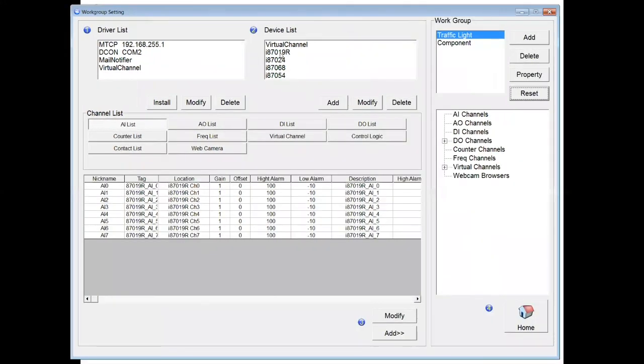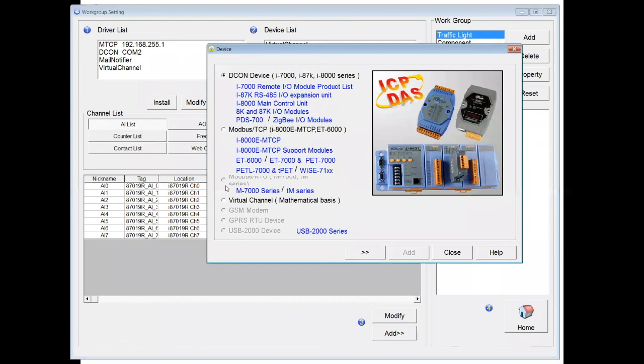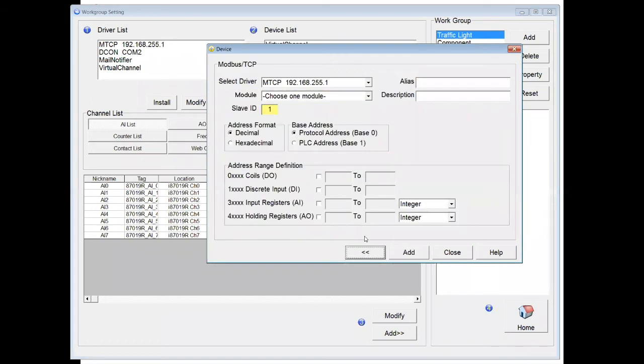So in the step where we add the module or device, let me go back here. In this example, it didn't have Modbus RTU, but it has Modbus TCP. So we just added a Modbus TCP device. So right here, where we put in the register types, like say it had 2 channels, you just select float here. And there's also float inverse if you had to do a byte swap. So you could do it this way. You just declare the input types as float values.